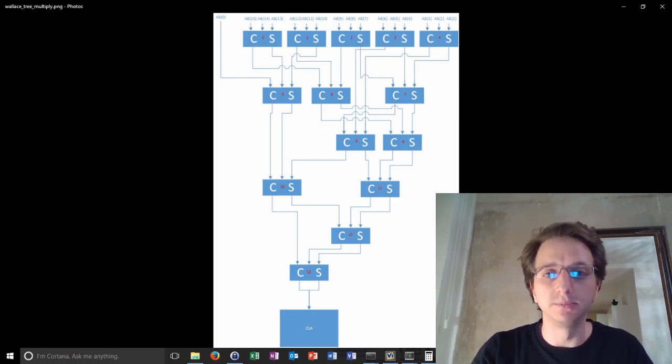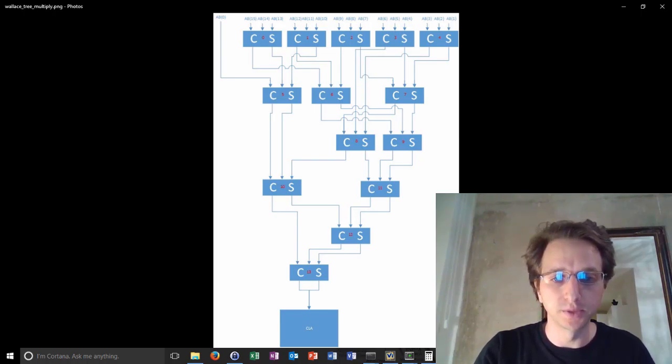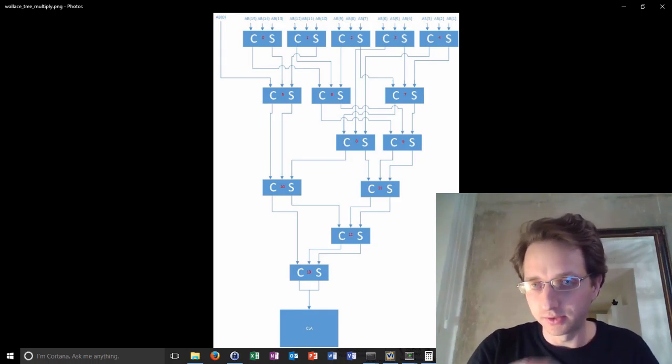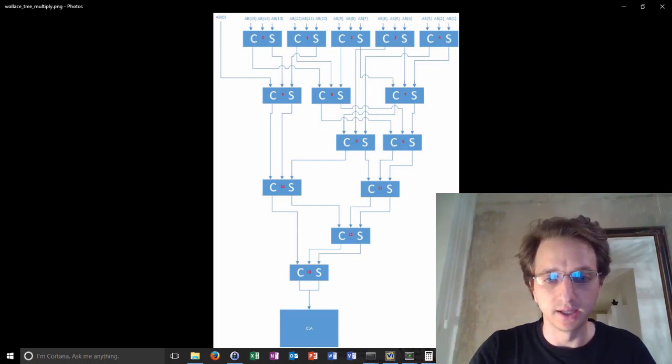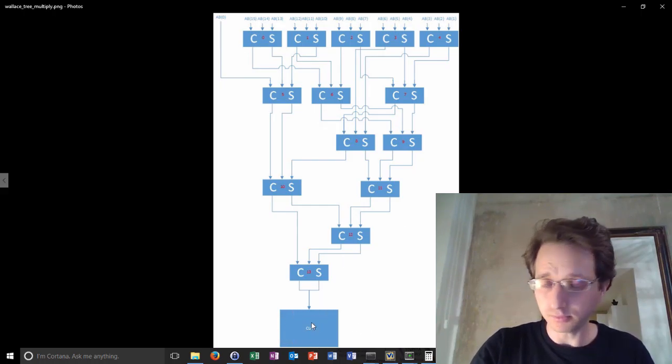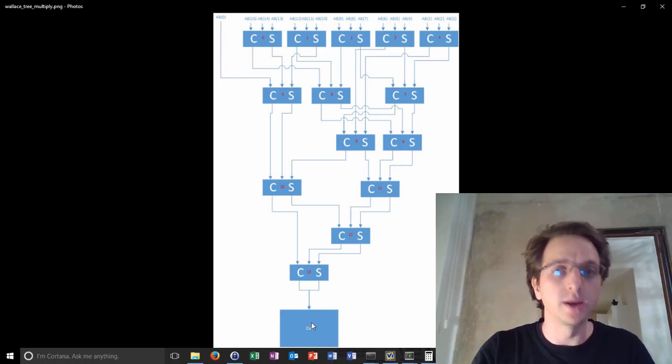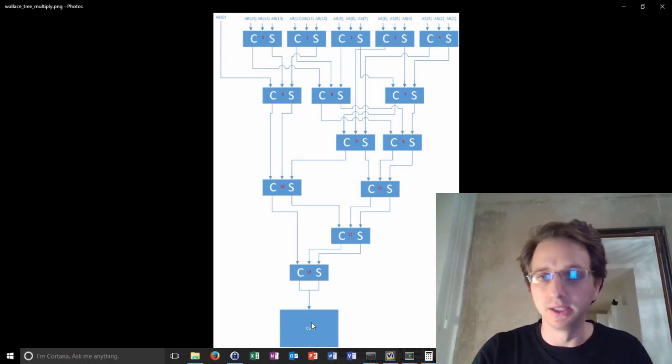The carry output and the sum output are of the 3 numbers, not just 2 numbers as for the full adder. So you can see you can make this Wallace tree, and I used 15 carry save adders, and then you finish it up with a regular full adder, and I'm able to multiply now in one cycle rather than probably the thousands that it was taking before.